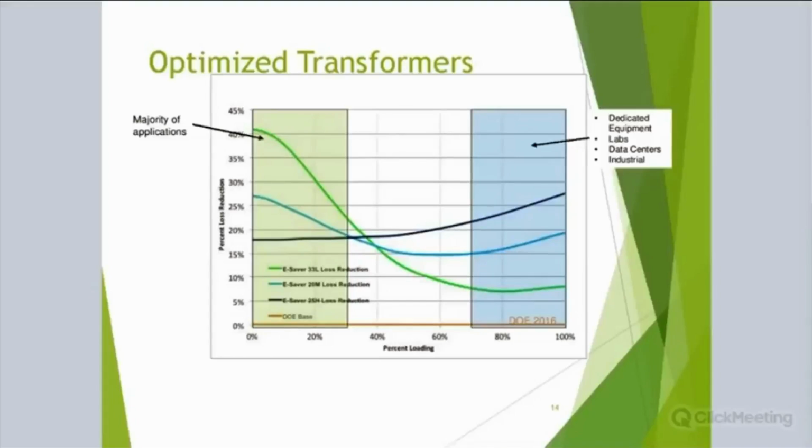All of these don't change the cost of the transformer, but they do change the internal construction of it. Where one transformer needs more of one construction design, the other one needs that in another area. So that's why most manufacturers that do this can provide different levels of transformers, applications of transformers for the same price. It's just where do they spend their money in the construction? So just keep that in mind.